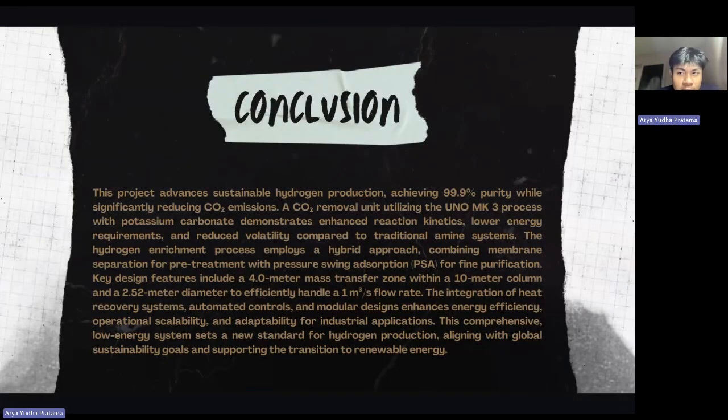Assalamualaikum warahmatullahi wabarakatuh. Hello, my name is Yudha Pratama. In conclusion, this project advanced sustainable hydrogen production, achieving 99.9% purity while significantly reducing CO2 emissions. A CO2 removal unit utilizing the UNO-MK3 process with potassium carbonate demonstrates enhanced reaction kinetics, lower energy requirements, and also reduced volatility compared to traditional amine systems.